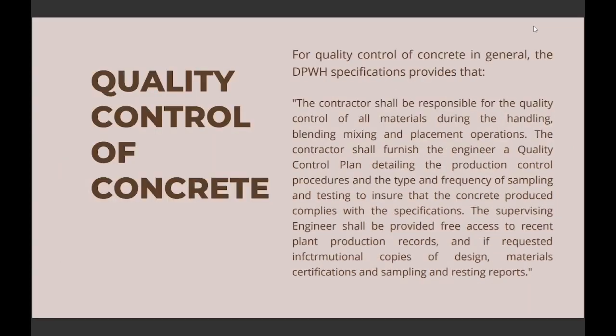So, quality control of concrete. For the quality control of concrete in general, the DPWH specification provides that the contractor shall be responsible for the quality control of all materials during the handling, blending, mixing, and placing operations. The contractor shall furnish the engineer a quality control plan detailing the production control procedures and the type and frequency of sampling and test to ensure the concrete produced complies with specifications.